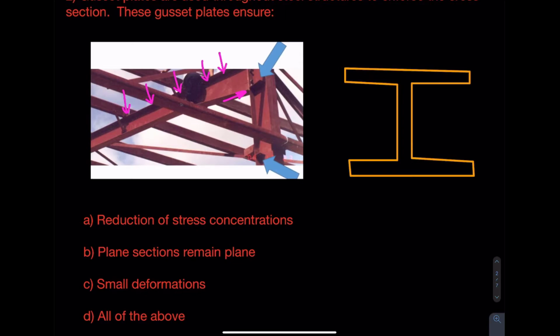So if we look at the picture here I drew on the right, this right here is the column. So I'm going to put column right here so you guys can know exactly what I'm talking about. And that'd be this cross section if I were to cut, let's say, right through there. So what happens is when this flange of the beam starts to compress on the column, it's going to create a bunch of forces on the flange of the column.